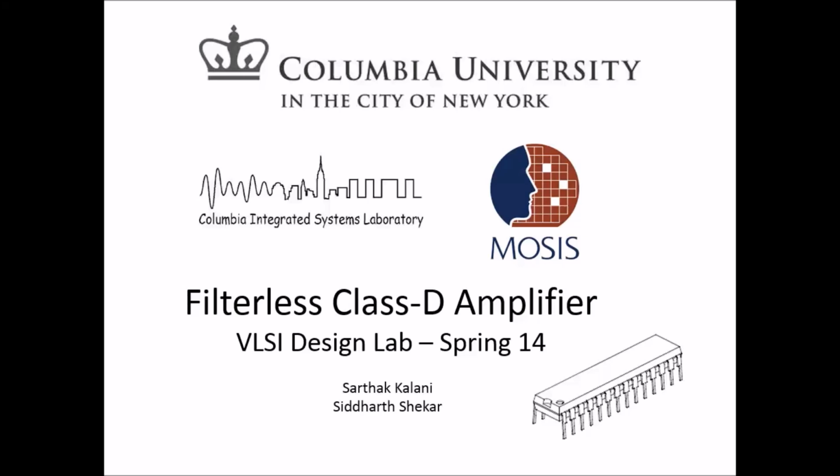I'll now be talking to you about the overview of the design of our chip. But before we get to that, I would like to give a brief background about the operation of Class D amplifiers. As opposed to Class A or Class B amplifiers, where the transistors in the output stage are used as small signal amplifiers, the output stage in a Class D amplifier uses the transistors as switches.